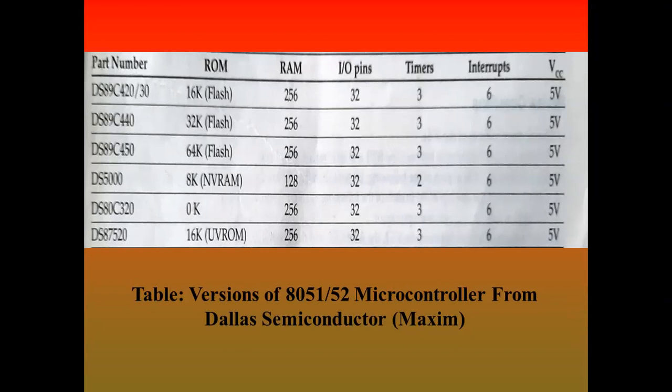So DS80C320 is the ROM-less version. As you can see, this is 0K. And also mentioned with that, the memory used, that is flash or the EEPROM or the NVRAM. So these are the various 8051 microcontrollers.